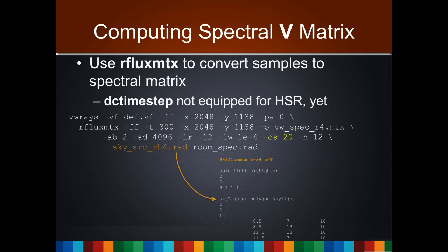This is the same, only instead of work plane points, we're giving it the rays corresponding to an image. We don't use the dash uppercase I option. We leave that off, and it interprets these as desired radiance ray evaluations. And vwrays just creates a collection of rays based on a view.